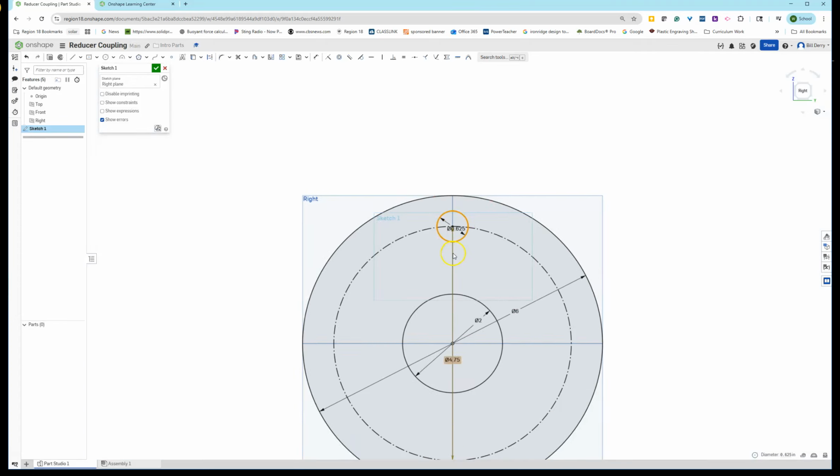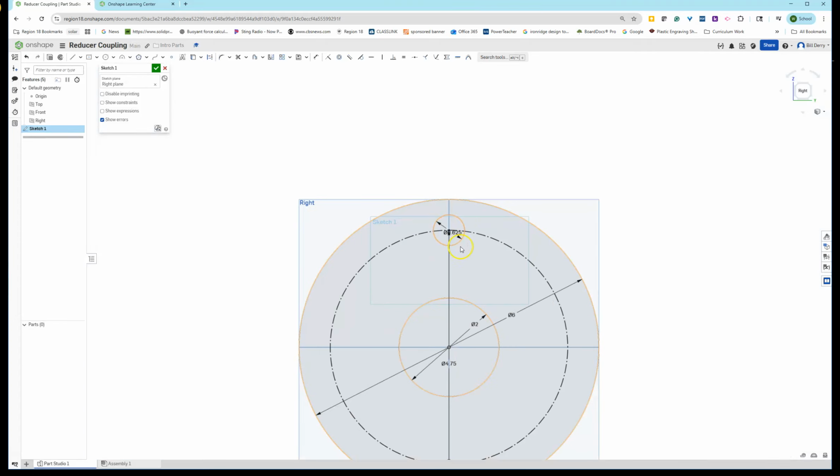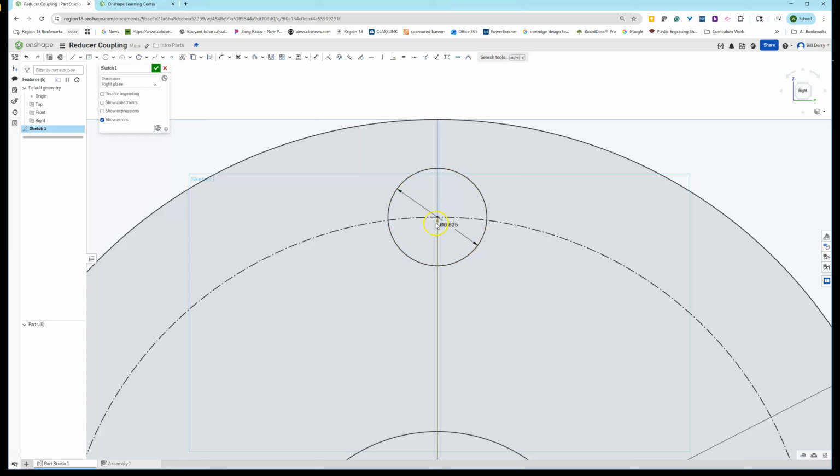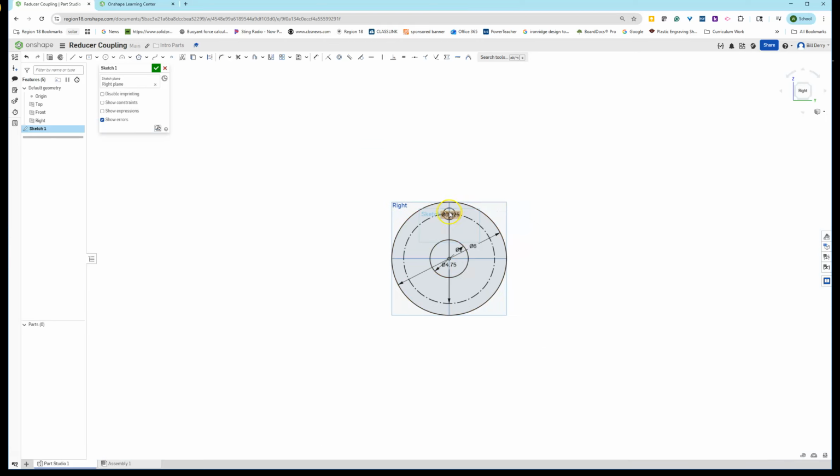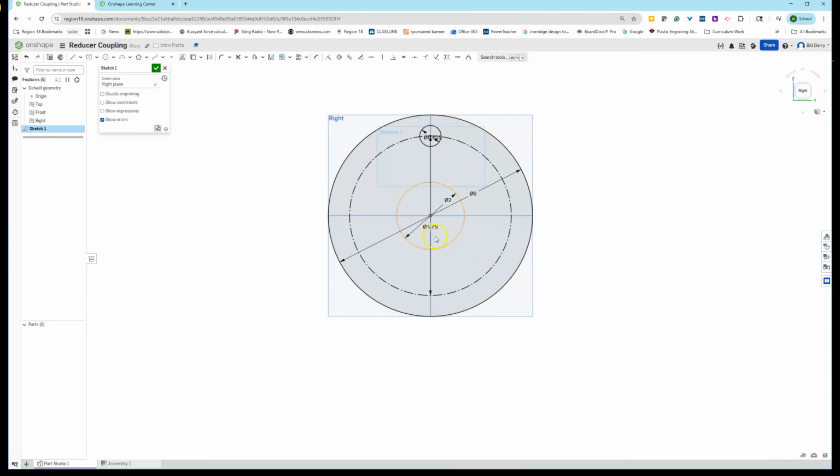not a construction line. Now you'll notice that mine is black, and the reason it's black is if I hover over this point, you can see that it's both coincident with this circle that's defined, and it is, if I hover over that again, and it's vertical over the origin. We're going to do the same thing with 3 more circles, although this one is going to be horizontal and coincident, and I'm not going to worry about size.